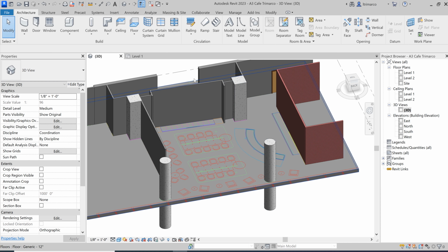And gosh, there's a couple ways of doing this, but I find the quickest for the time being is literally selecting it and then going to the glasses at the bottom of your interface in Revit, which is called hide and isolate. I select it and I just say hide. Another way you can do it, I'm just going to hit Control Z right now to undo what I did.